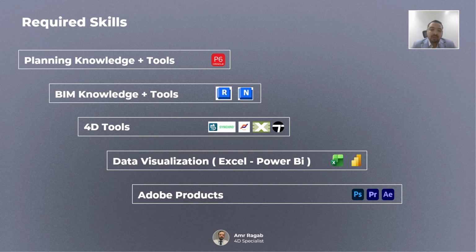You can export it with structural columns and slabs and everything. So you have an Excel sheet for your Revit model, and you have an Excel sheet for your baseline. If you are an Excel expert, you can integrate them together. And if you are a Revit API developer, or you have skills in Dynamo, you can make something good with these two sheets.